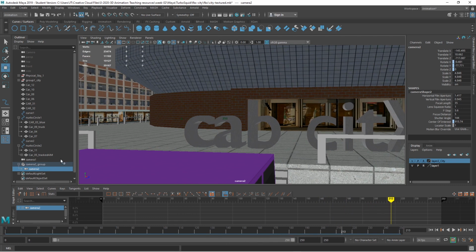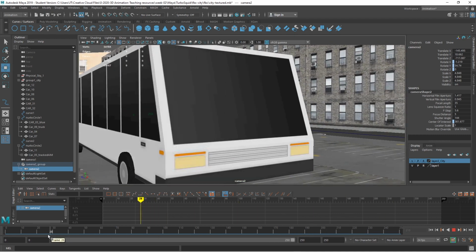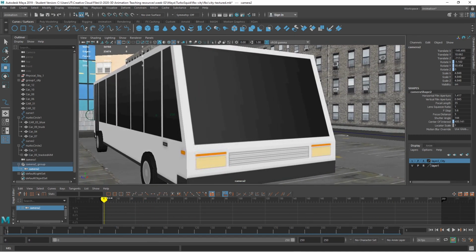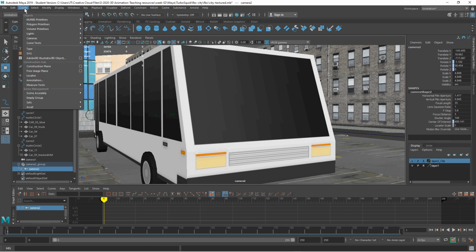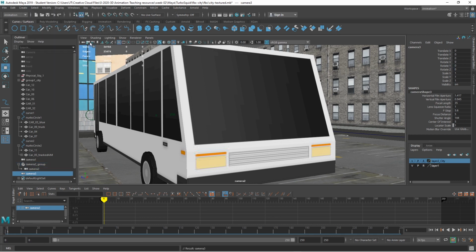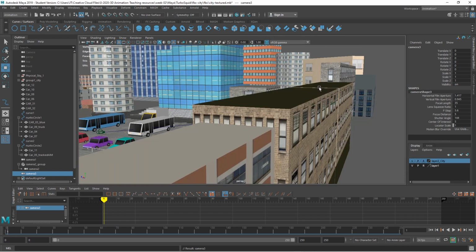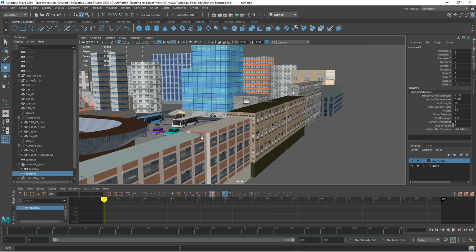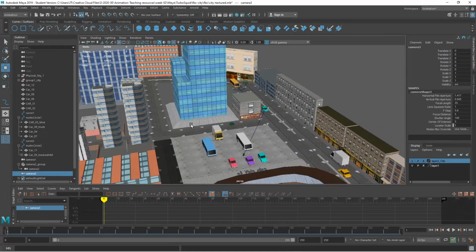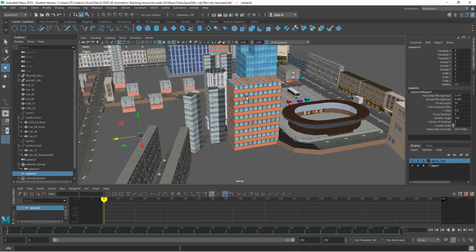So that's the second type of camera, the camera and aim group. The last thing I'm going to show you is another normal standard camera. So I'll make a camera, and I'm going to make sure I'm not moving in this window, because if I do make changes in these windows, which are the cameras I'm setting up, then it will actually change where I set my camera. So I'm always going to move around in the perspective view. It's quite an important part of knowing what's going on.